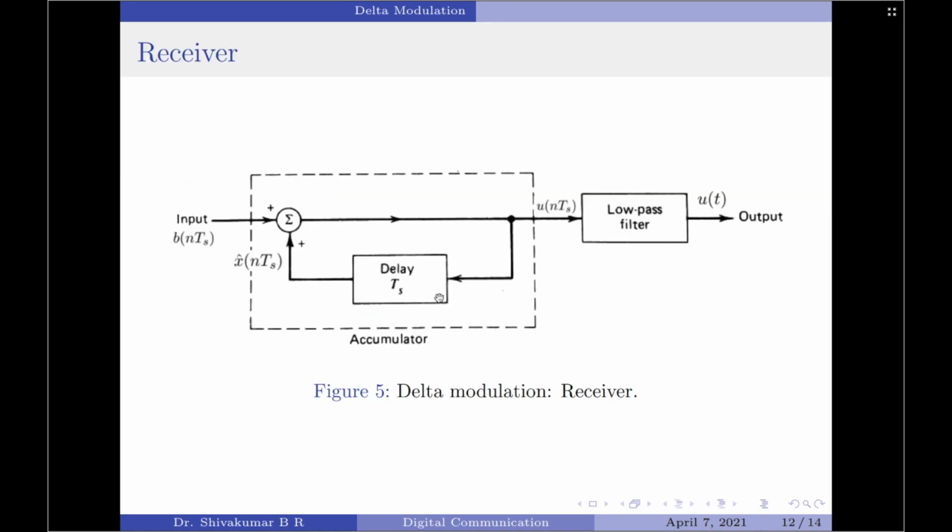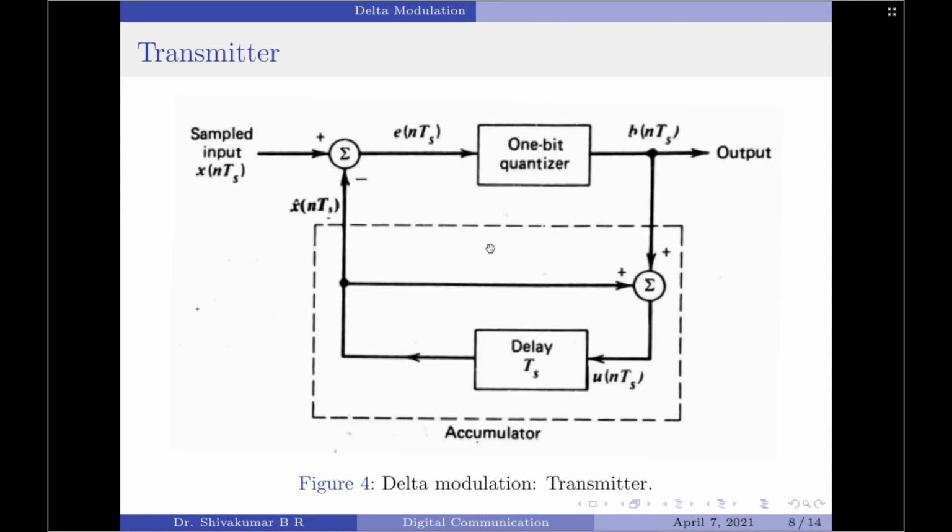By comparing the differential pulse code modulation and the delta modulation receiver diagrams, we will see that except for an output low pass filter, delta modulation in fact can be considered as a special case of differential pulse code modulation. You should note, delta modulation particularly offers two unique features compared to DPCM. The first one is the use of the 1-bit code word for the output.